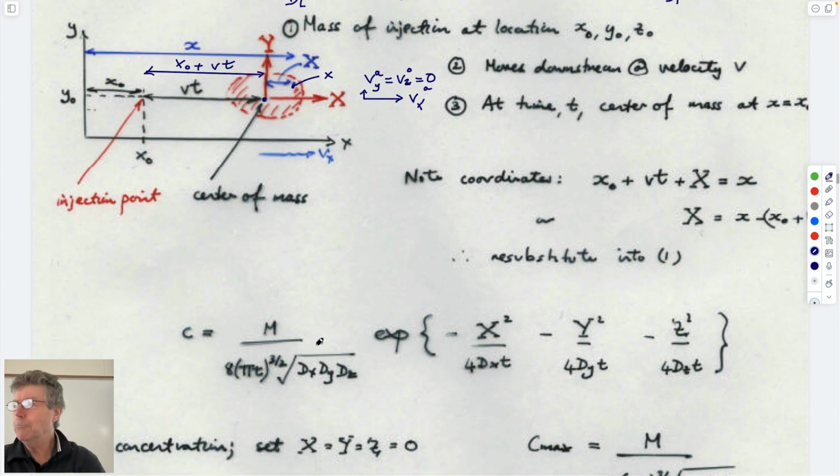So if you think about a moving frame of reference, talked about that before, right? If you attach yourself to this center of mass of the plume, you know that you're going down gradient at the advective velocity. You know that in 10 minutes, if you multiply the advective velocity by 10 minutes, you know how far you'll be. And then the plume is merely relative to that coordinate system in uppercase X and Y coordinate system. Much easier way to think about it.